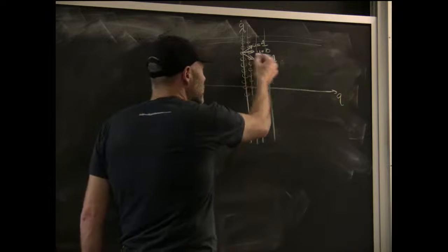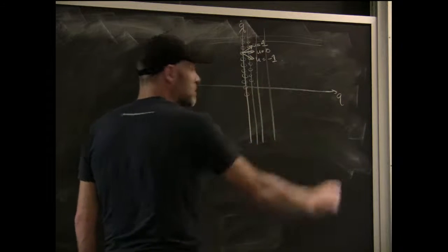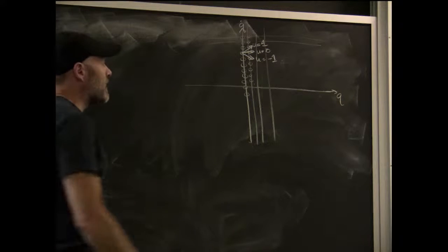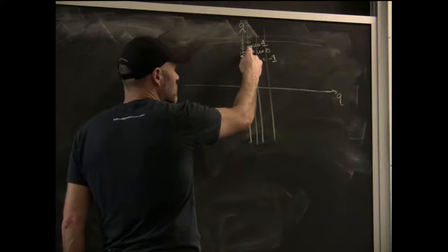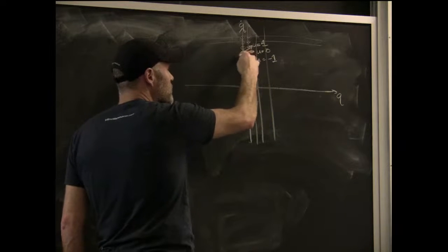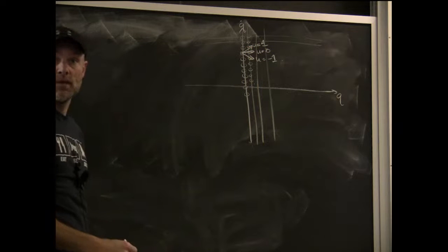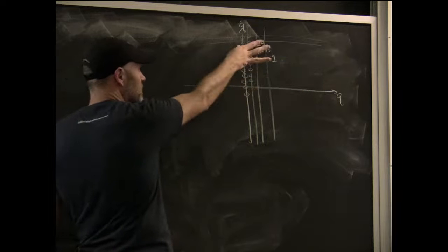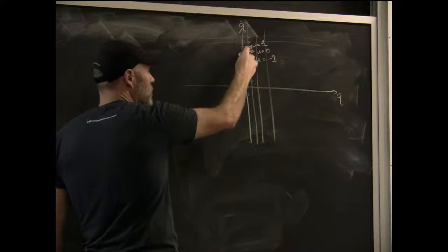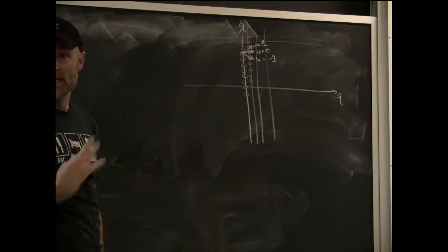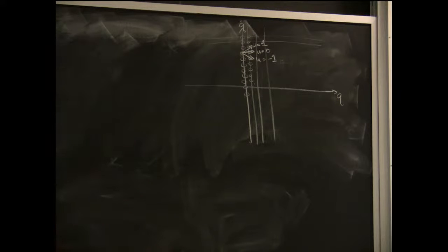Okay, and I can construct a graph that lives right on top of that state space. The only way that my dynamics comes in is the way that I connect the graph. Given the equations of motion of my double integrator in this case, I can have arrows to some neighboring cells and not to others. That's the only way that the dynamics comes in.